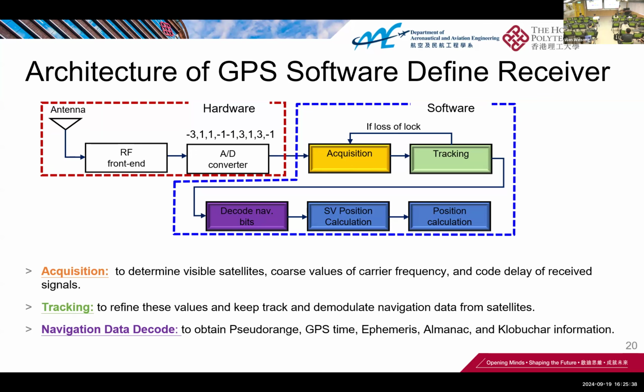So this is roughly the idea behind the GPS receiver architecture. In this lecture, we are going to focus on the position calculation. The satellite position is a known variable; you can directly decode it from the satellite navigation data. For the user position, we calculate the receiver position through an estimation technique, the gradient descent or the least squares process, in the coming slides.